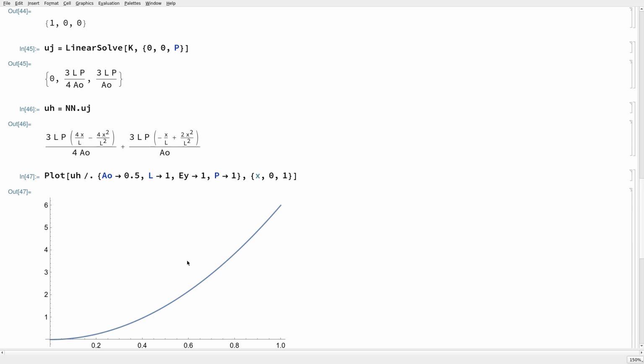Get a better interpolant. What the previous result was saying was that, even though my section is conic going down to 0, the displacement field across the length of it was linear. But we know that can't be true, because a linear displacement field would be a uniform displacement. If you're making the cross section smaller as you get towards the end, its resistance to deforming is going down, because you have less section modulus to resist the deformation.